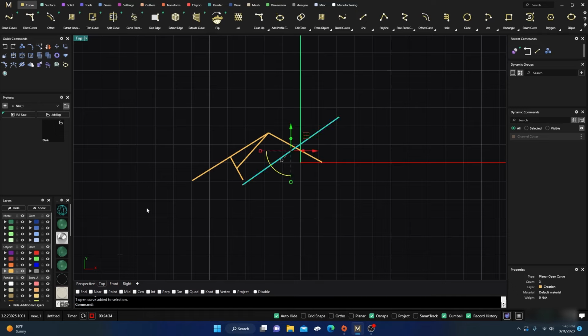especially if you're doing booleans, which is cutting things, and you say, okay, I want all this color here, the cutting layer. So that's a cutting layer. You think that's the only one you have, but maybe you have a duplicate, and you collect all of them and try to do a boolean. It'll blow on you sometimes. So maybe check to see if there's any kind of duplicate objects.